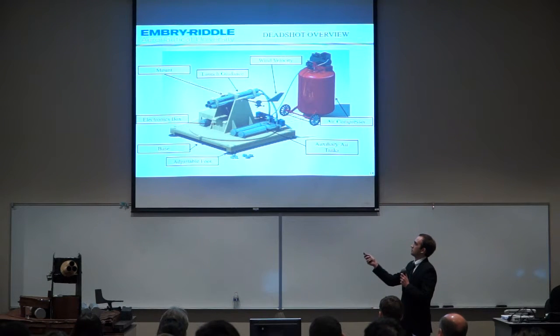This will aim the system, and then when we're ready to fire in elevation, it'll be raised. These barrels will be raised by the elevation mechanism on the side. And then to fire, the compressed air will be released through the auxiliary air tanks, through those barrels, and fire.